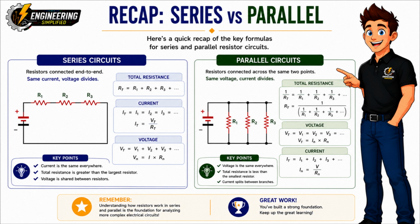The total resistance is simply the sum of all the resistor values, and the supply voltage is shared or divided across the resistors. Now let's compare that with parallel circuits. In a parallel circuit, every resistor is connected across the same 2 points. Because of this, every branch has the same voltage across it. The current divides between the branches depending on the resistance of each branch. The total current is the sum of all the branch currents, and the total resistance is always less than the smallest individual resistor in the network.